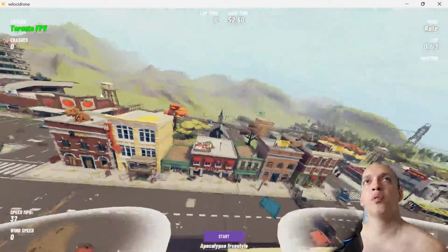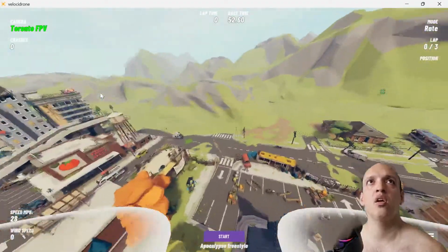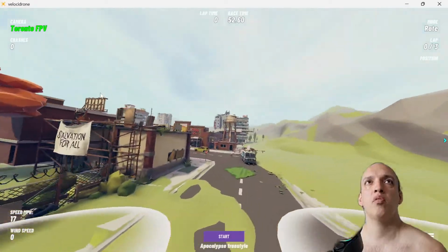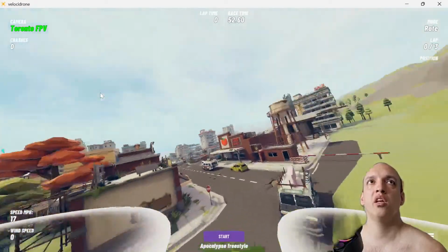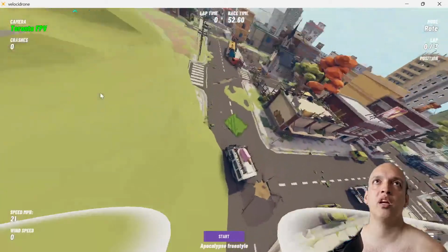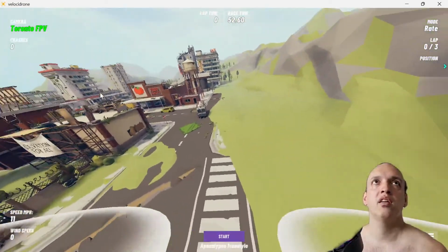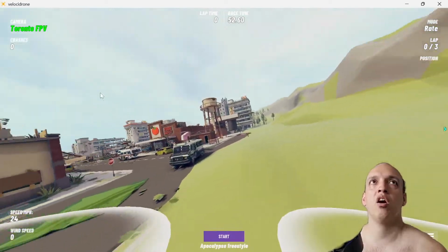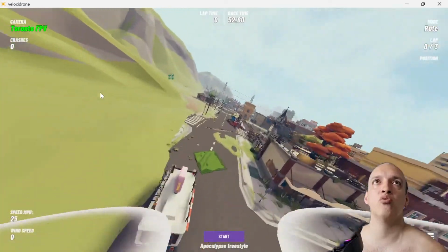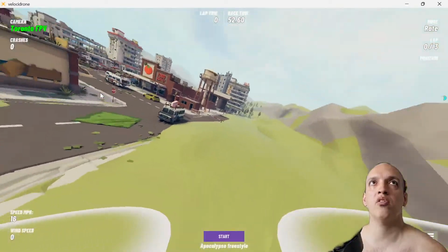I don't know if you ever played video games, you know how to strafe, like when you go around a turn. Because look, we can go here and we can go straight, and then with our yaw, we can yaw this way. But see, we're still moving in that direction. We got to always use those propellers to pull us where we want to go. But see, sometimes people think, okay, they yaw this way. I'm like, wait a sec, I'm not going that way. I'm still drifting. So if you want to be able to go that way, you got to use yaw and roll together and then smoothly.